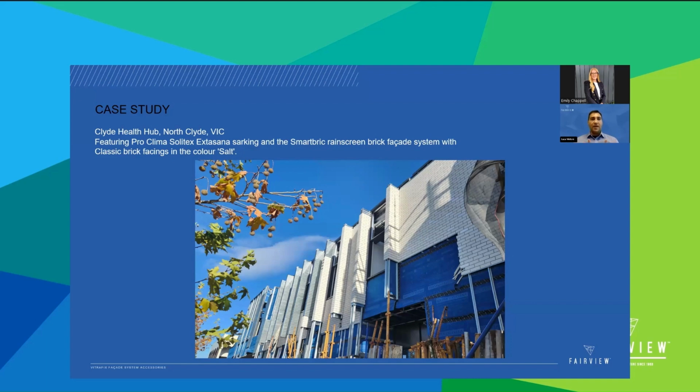What happens is that they will act only in case of fire. So usually you have an open cavity, but a minimum thickness is left open between the cladding and the fire cavity barrier. In case of fire, the fire cavity barrier will expand, closing the gap. So the restricted depth of the cavity is just at floor level, equal to the height of the fire cavity barrier. The rest of the cavity is full depth, so the air can keep circulating behind.